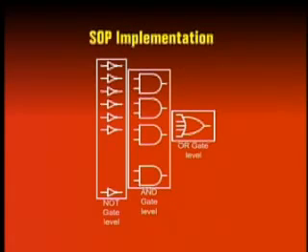The AND gates produce the product terms, output of all the AND gates are connected to a single multiple input OR gate for sum of products. The product terms comprise of literals in their complemented form and uncomplemented form, which are implemented by NOT gates connected to the inputs of the AND gates.